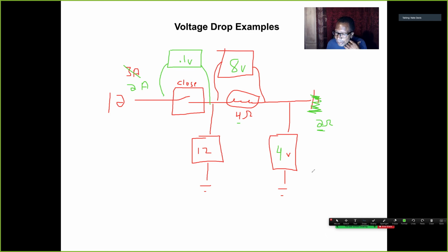Like we said earlier with the TPS, it's going to require 4 volts to push the current through a resistor down line, which is this. But now the problem isn't on the feed side circuit, it's on the ground circuit. And you can tell what side the problem's on by doing the voltage drop. But guess what? The part is still affected the same way. The part is being robbed of voltage either on the feed side, we showed you earlier, or the ground side, which I'm showing you now.